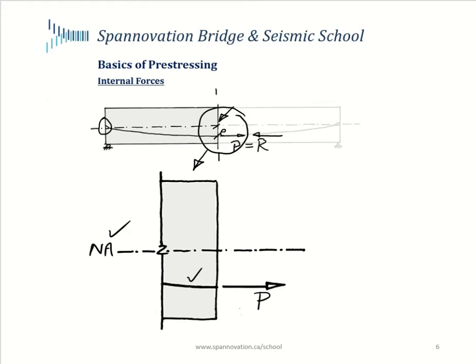Now, what this does is, as it pulls this left portion of the beam, it's pulling it against the right portion of the beam. So that's the right portion, and there's bearing between the two faces, and there's a whole bunch of little reactive compressive forces amongst them. And if I were to add all of these up, there would be this net compressive force, and that compressive force, or the reactive force, as I'd shown earlier, should be equal in magnitude to the force in the tendon, and it should be sitting exactly at the same location at eccentricity e.